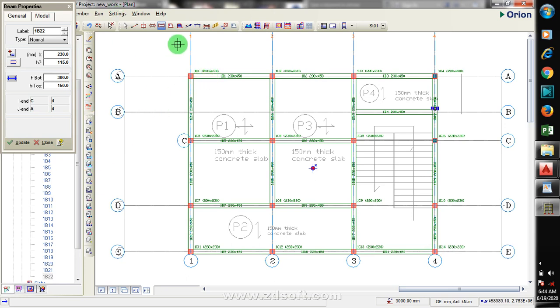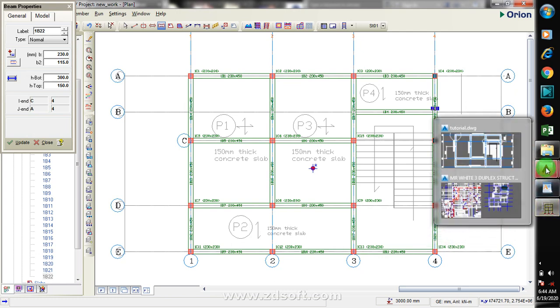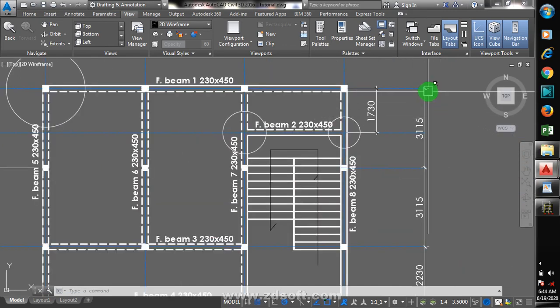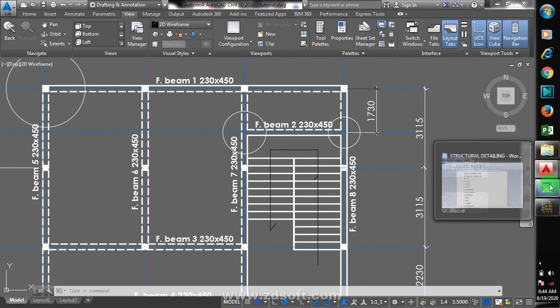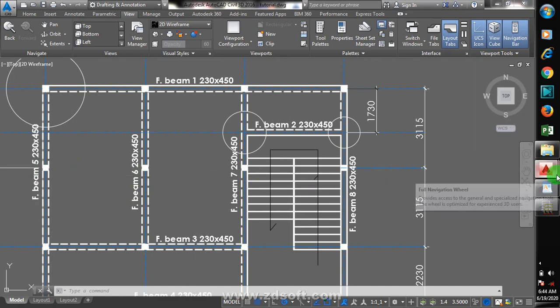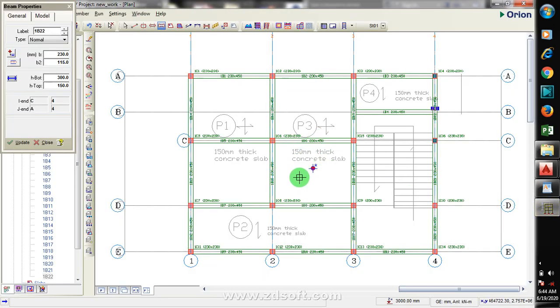Now I'm going to be introducing my slabs, my panels. Now I introduce a beam across this because the span from here is actually very large. It will be good to introduce a drop beam. There is more to structural design that you need to know, most especially if you're a beginner. You can see if I take from here to here, this is around 6,230, which is a very great length. There are some other solutions, just in case I don't want to introduce a drop beam here, but in this video I'm not going deep into that. I'm just going to do it the way it is right now.